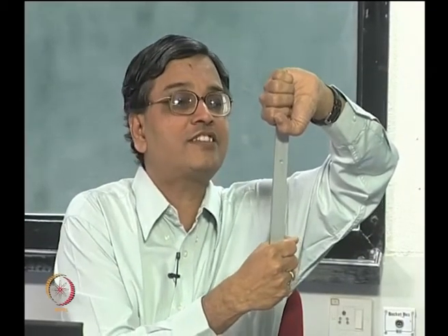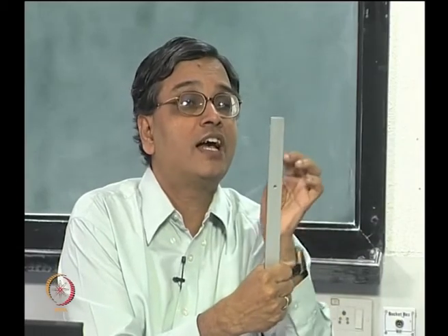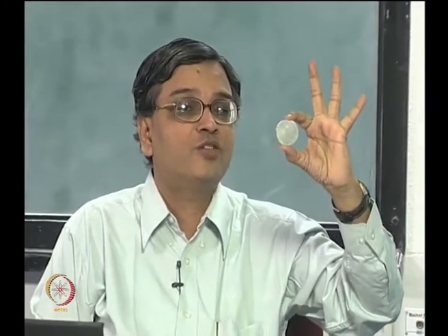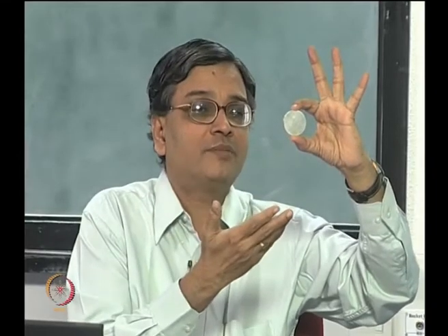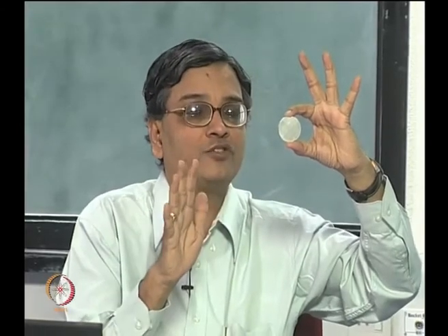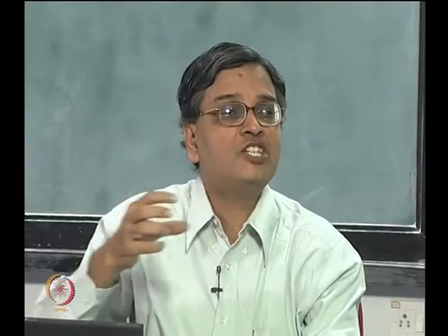Even in theory of elasticity, the hole should be as small as possible, okay. And on the other hand, even if you change the geometry, I do not have a hole here, but the geometry is changed, because of the way I apply the load, plane sections do not remain plane before and after loading. So, when I move from strength of materials to theory of elasticity, I have enlarged my domain of solving problems.